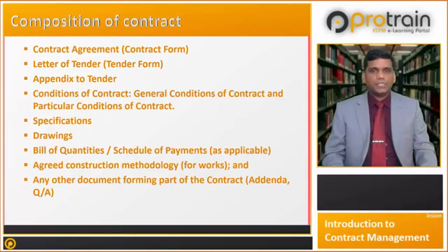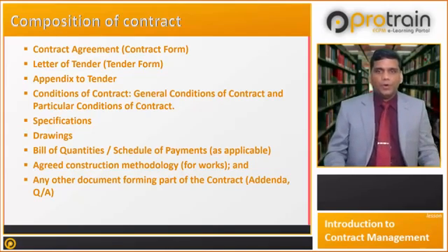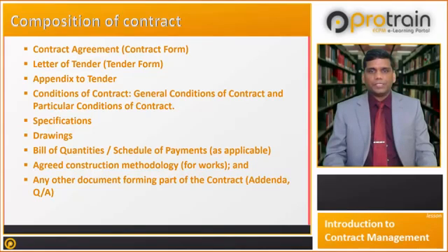Particular conditions change, replace, and revise the clauses of the general conditions. Particular conditions should be in line with the local law and the law of the contract. Clauses in particular conditions should not conflict with the clauses of the general conditions. Any revision, additions, omissions done by the particular conditions should be based on rational reasoning. Priority of documents is very important and it should be readdressed for every project through particular conditions.